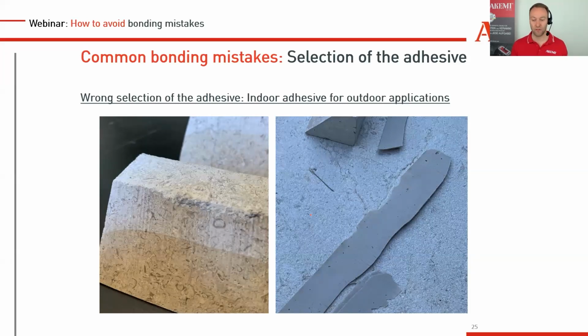If it comes to outdoor, use an epoxy or a proper polyurethane. I know in some warm areas, let's say southern Europe, like southern Spain, or India, for example, they sometimes also use polyesters for outside bondings and fillings. This works there more or less, because they only have heat, between 20 and 35 degree temperature changes. So this could work, but as soon as it drops to 0 and water comes into play, then you will have problems. So better stay with epoxies or polyurethane for outside applications.